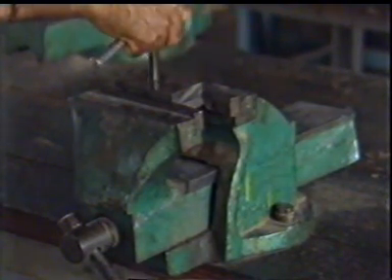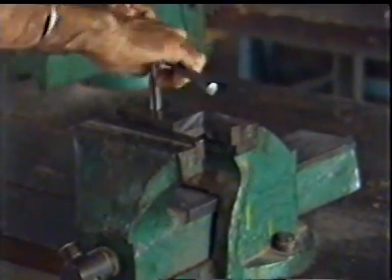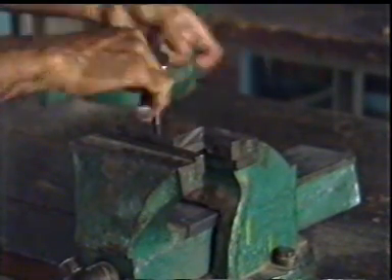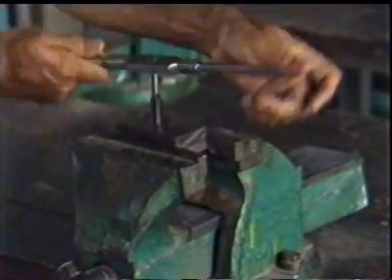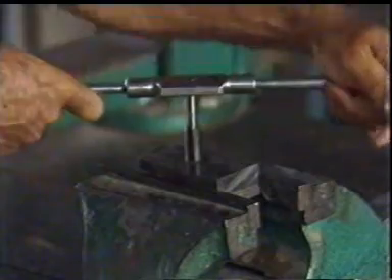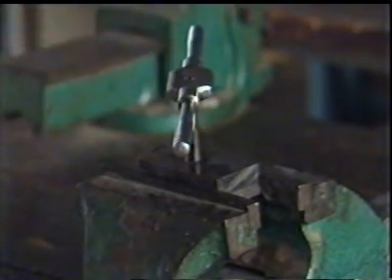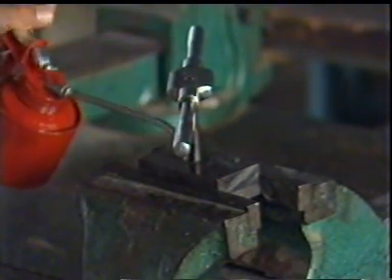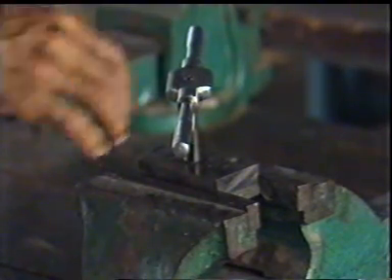After the taper tap, the process is repeated with a plug tap. This will produce the threads closer to the required size. During the operation, lubricating oil must be used for smooth cutting and to avoid damage to the tap.